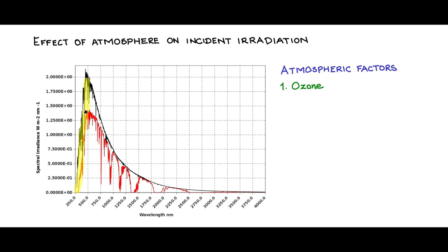And if you go down in frequency, or higher in wavelength, there is attenuation due to other gases, clouds, carbon dioxide, and also water vapor. You can probably see that there are some deep notches here, where the attenuation in these bands is very significant, almost down to zero. These notches, which I have indicated in green, are due to the water vapor content in the vertical column of air above the collector.